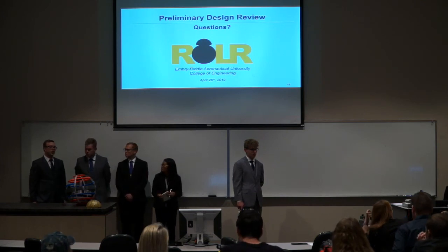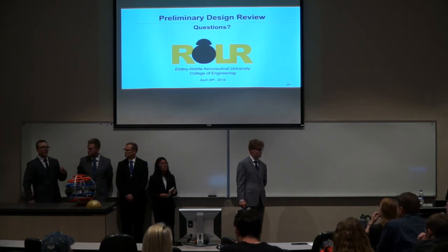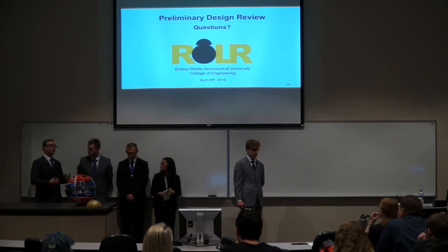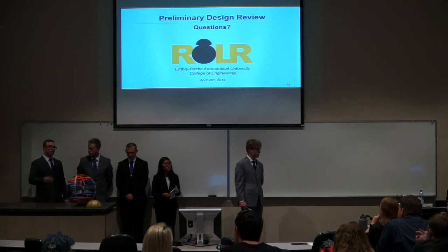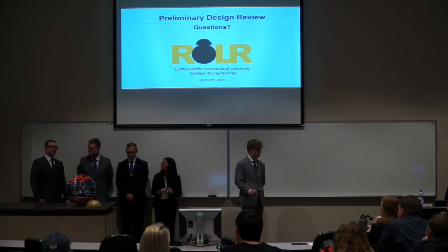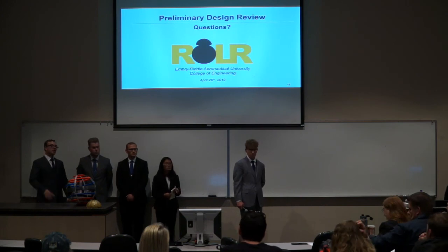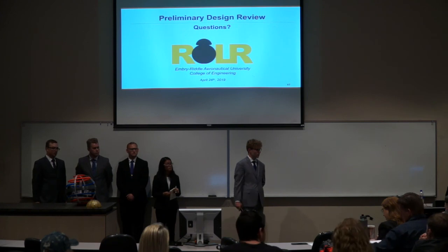For the sake of time, we actually had a much longer presentation we gave last week, in that we did detail all of our analyses. I performed a link budget analysis on what I thought was the weakest link, the lowest power, highest frequency component that would propagate as well. With that, we got a maximum effective range of 860 meters. So given our max range of 350 meters, and that being the weakest link, I think all the other components should satisfy that. All right, sounds good.